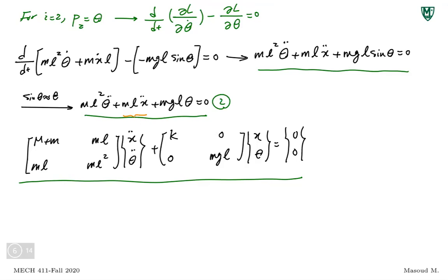As long as you can find those coordinate systems for your physical system, like by just looking, which usually don't exist that easily, you're fine. You don't even need to do modal analysis. But modal space guarantees that it finds a set of coordinates that decouples the equations of motion, so it makes your life much easier to solve those.